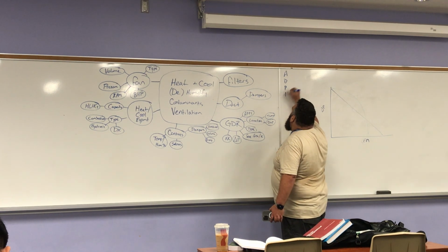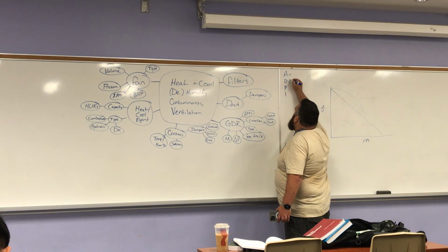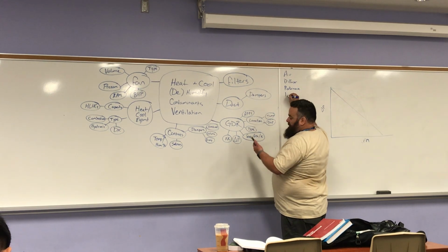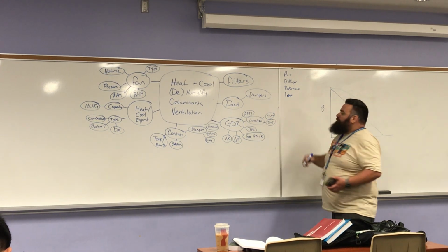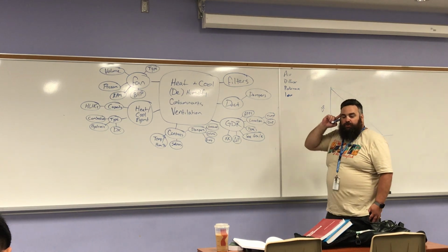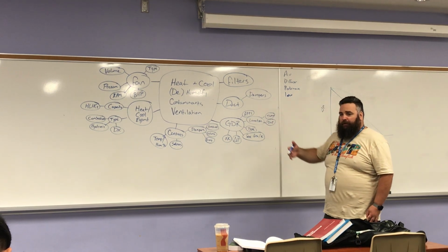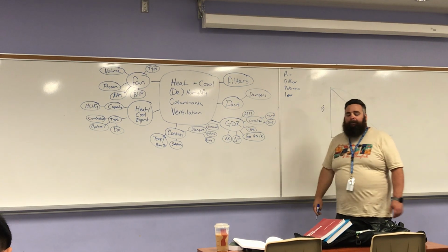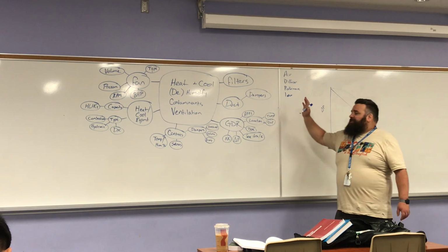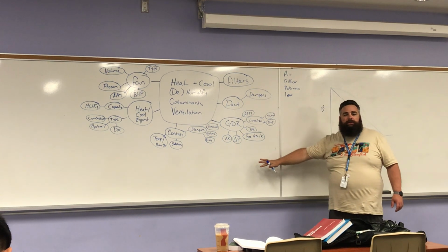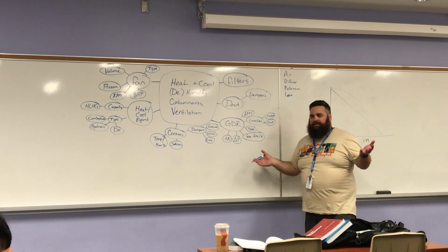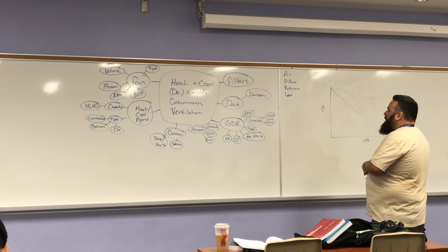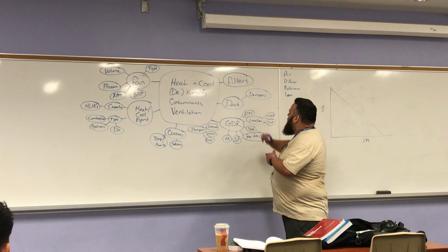And that relates to the function or the dispersal pattern of that diffuser, and that's actually based on cold air. We don't have published ADPI for hot air. This is all stuff that we're gonna cover throughout this course, so we're just trying to get a sense for all the things that we need to consider when we're designing a system here. That should be ADPI, not APPI.